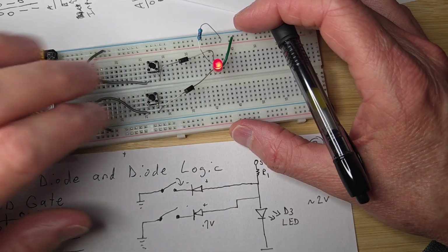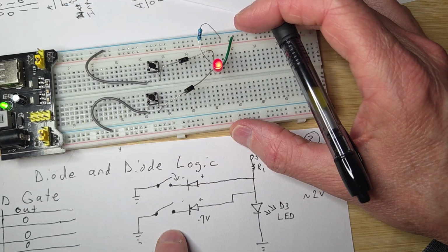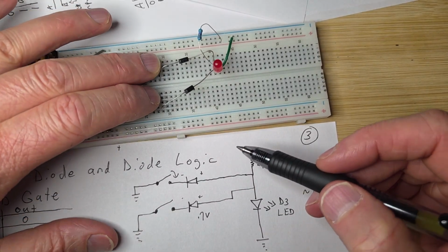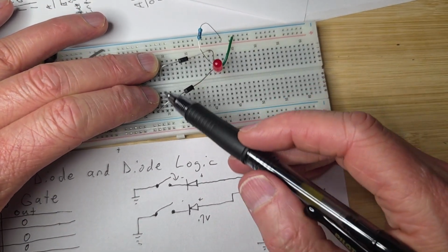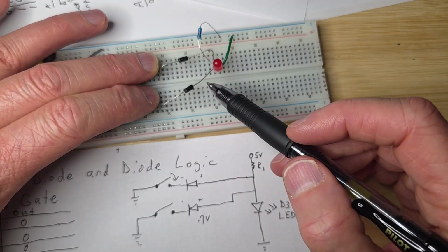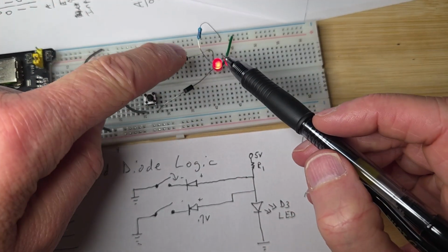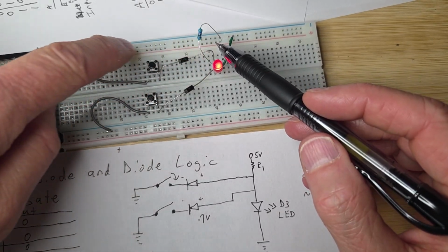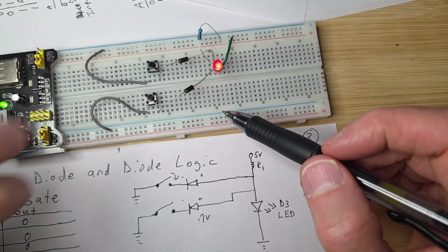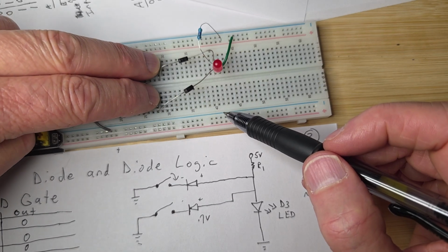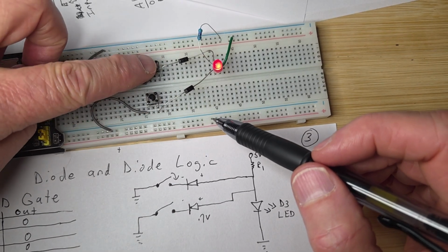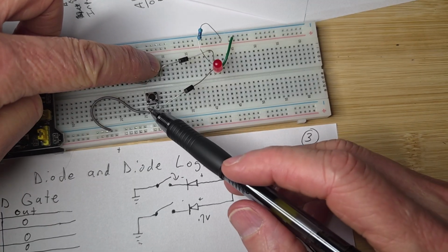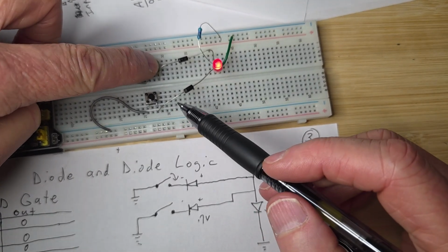Now if we go zeros, by pushing them in, when I make contact, it's going to bring them both to ground and turn it off, because I'm shorting across that LED. When I push a button, the current decides it's not going to turn on the LED. It's going to go around and go to ground every time. So this would be 0 0, and then A. This is A, so A is 0. This is still high, because we're considering it high.